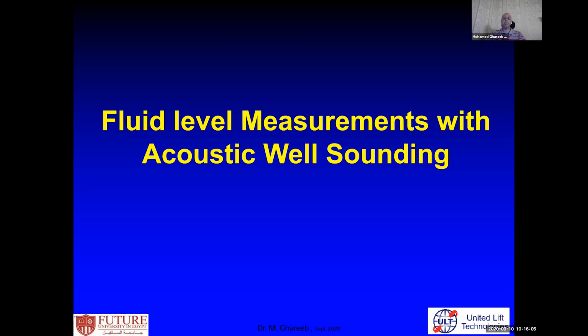He simulated moving your load cell to the top of the pump, eliminating all the effect of the friction between rod and tubing, the weight of the rods, and the geometry of the pumping units, and gives you the net fluid load over the pump, which you can use to analyze your downhole pumps.